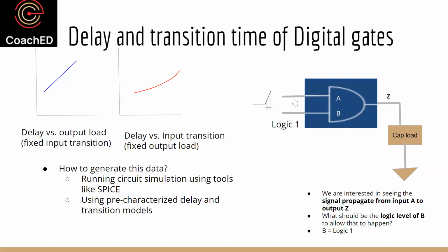In combinational gates, the timing arcs are, most of the time, between input and output. If it's sequential logic, like a flip-flop or a latch, there are 2 kinds of arcs. One is an arc between, let's say, the data and the clock, which is an input side arc.